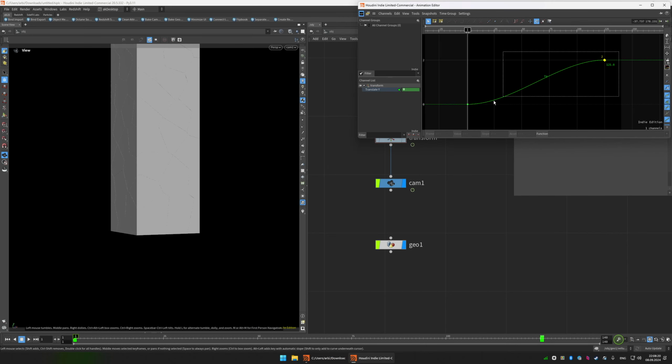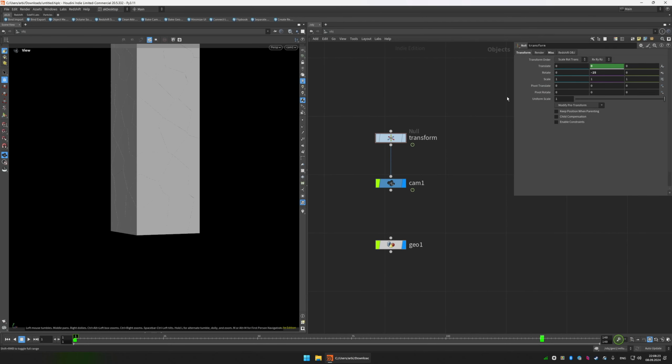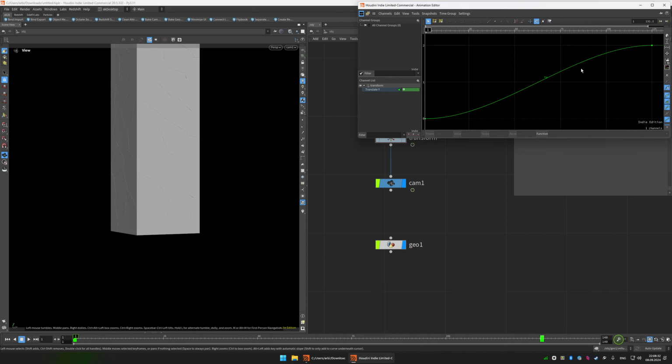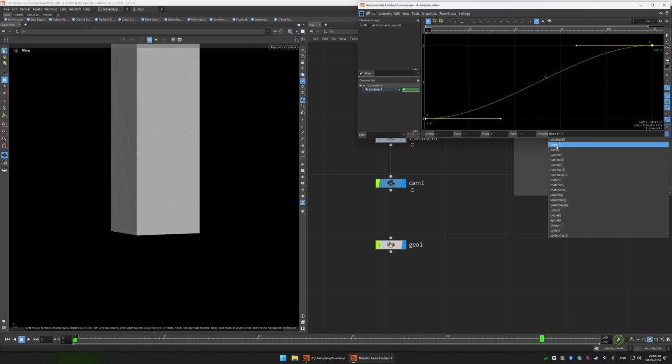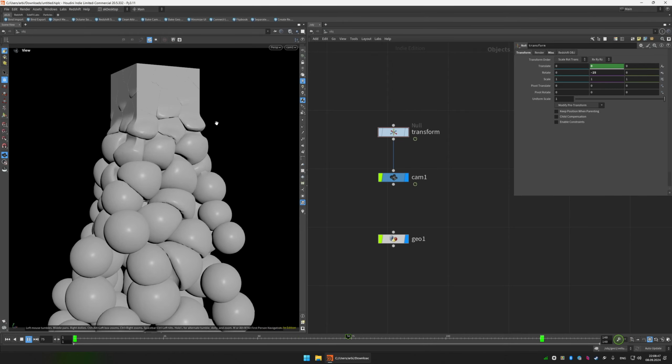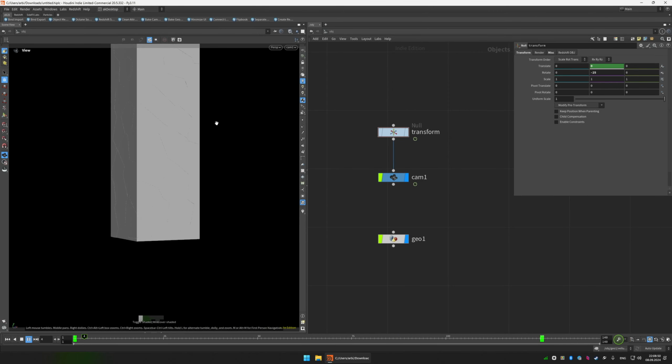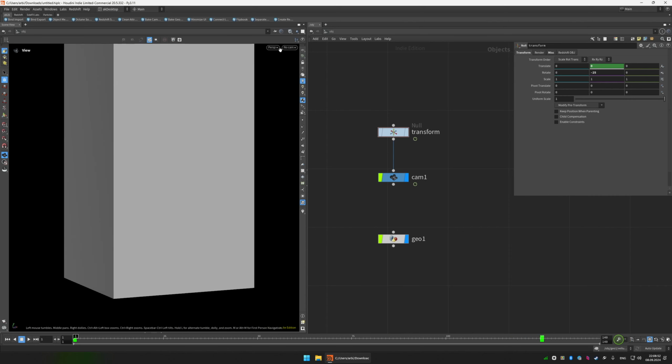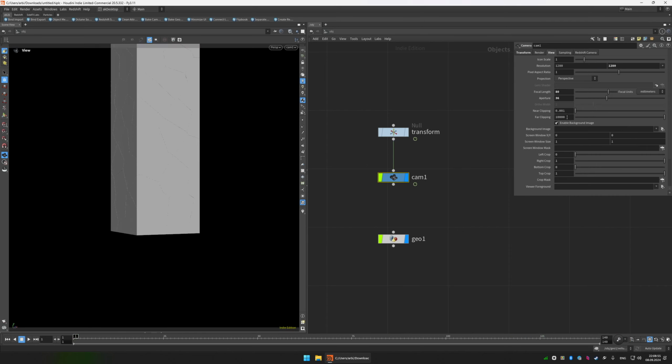and then of course I want the easing to be linear. Basically you can set the keyframe with the Alt key, just what I did, and then if you press Shift and the left mouse button, you can get this animation editor, and if you press Ctrl A and choose linear, you want to set this easing to be linear, so it goes up, and that's it. And here, as you can see, this weird behavior in the camera. What you have to do is just raise the near clipping here, and it will fix this problem. So this is the camera.